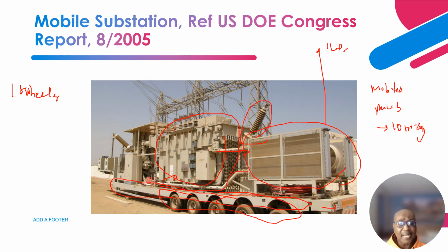It gets heated by the winding that is hot, and it takes the heat from the winding through a conduction process. Then the hot oil rises up due to a convection action.